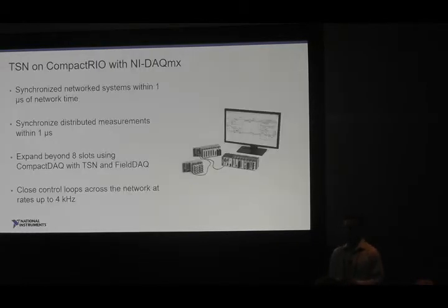And so looking at TSN specifically on CompactRIO with NI DAQmx and some of the key features here, again, as we look at that synchronization aspect of it, that's going to cover the first several bullets here. So you can synchronize distributed systems. So now if I have a CompactRIO controller over here, and I can run a CompactRIO controller over here, they'll be synchronized if I'm connecting over Ethernet through a TSN supported chain. So I can have synchronized systems, which I can then synchronize my measurements based on, so with DAQmx, I can acquire measurement data and make sure that I'm getting the data at the same time across this bigger distributed architecture. Or also just run tasks at the same time if I want to do that as well.